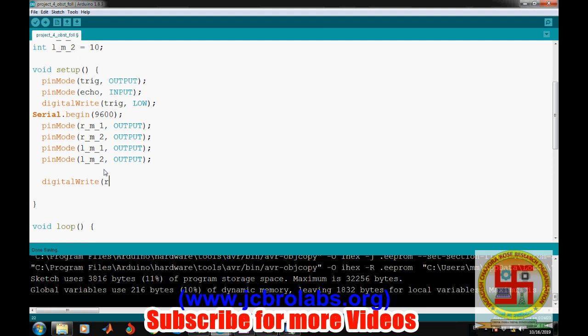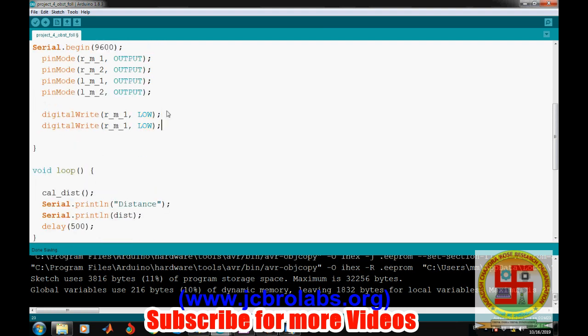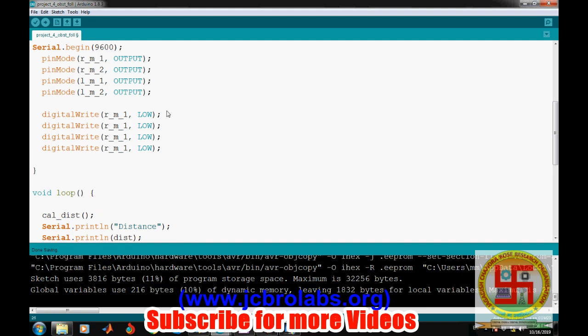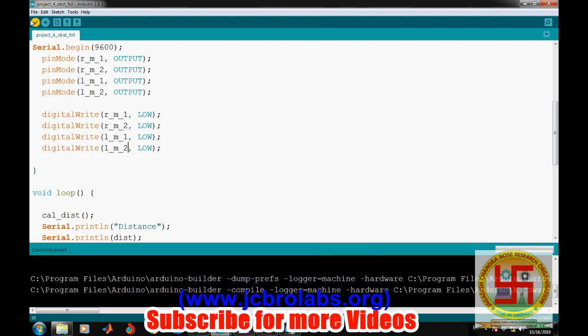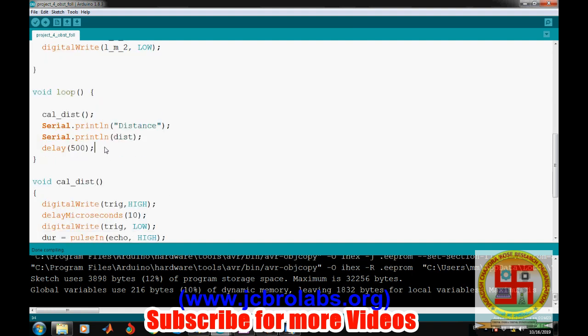So digital write R underscore M underscore 1 comma low. Okay, so digital write to left motor 1, left motor 2. Okay, so let's compile it. Let's see, hope there should not be any error. Okay, then compiling. Now we will write a program in void loop.